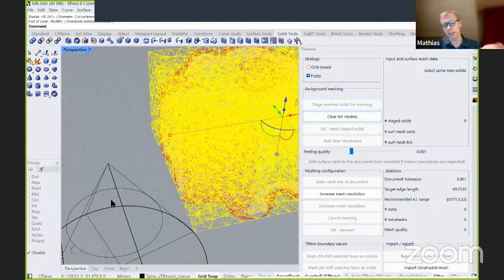So in topology optimization, excess material is removed, and then people do the FEA again. So they are always based on a usage measure. I forgot the term that Karamba uses, but Karamba puts stress states into something that they call usage. Karamba has a term for the degree to which a certain volume element is an excess volume element. But I think topology optimization is a great example.